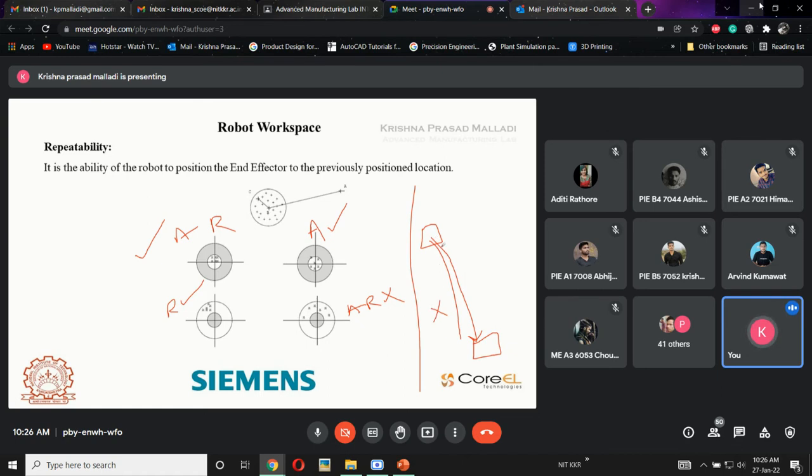So you have to run this program for even 20 cycles or 10 cycles on a test basis. What will happen? You have to check whether the final operation you are going to maintain has accuracy as well as repeatability or not. You have to check thoroughly. Otherwise, suppose you have checked one application, two applications, and in both it is performing well, so you give this application for 100 runs or 200 runs. What will happen? Maybe after 10 runs, after 20 runs, because repeatability is not maintaining the accuracy, the spot you are going to do here will finally come at this location.